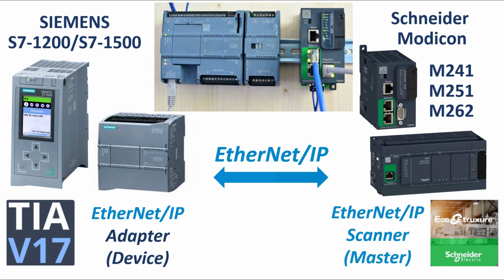In recent years, Schneider Modicon released the M241, M251, and M262, this new platform of controllers, and their new software named EtherNet Expert. These controllers have EtherNet IP scanner and EtherNet IP adapter functions. Also, for the Siemens S7-1200 and 1500 PLC, other than their built-in PROFINET, Siemens also released a solution enabling the Siemens controller to run EtherNet IP scanner and adapter.